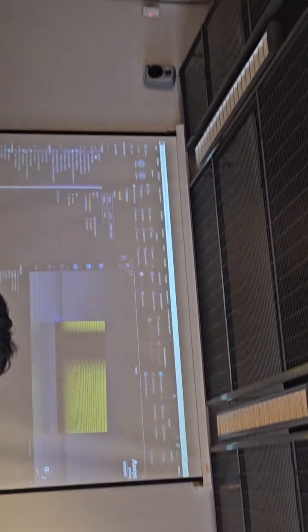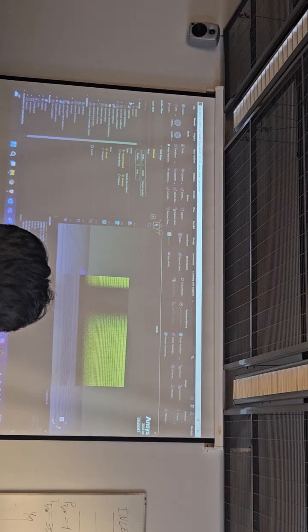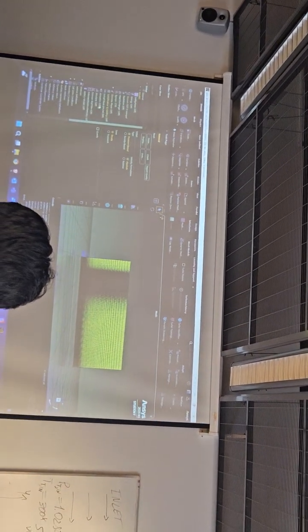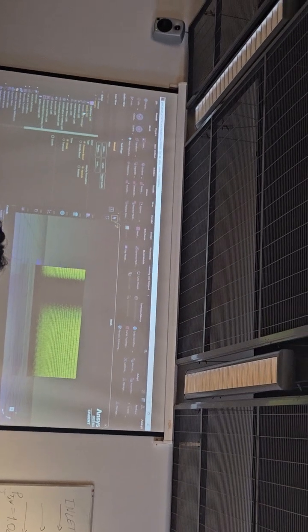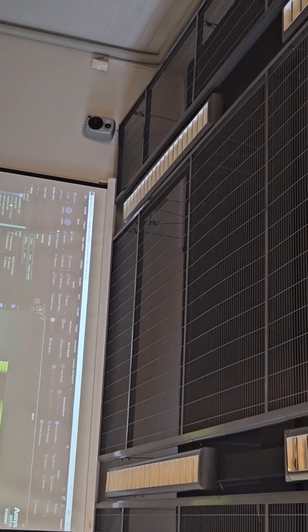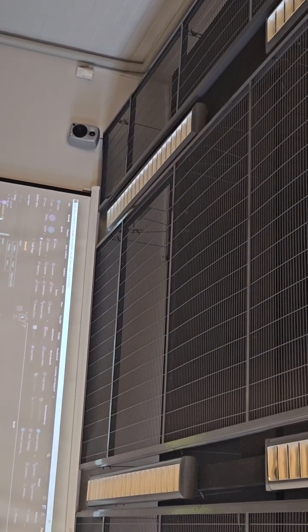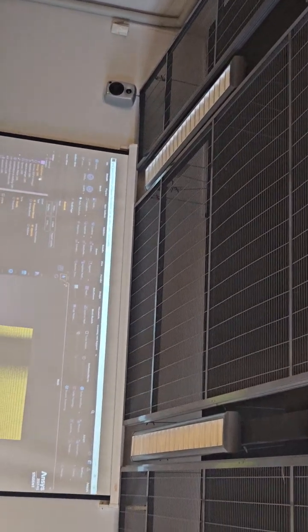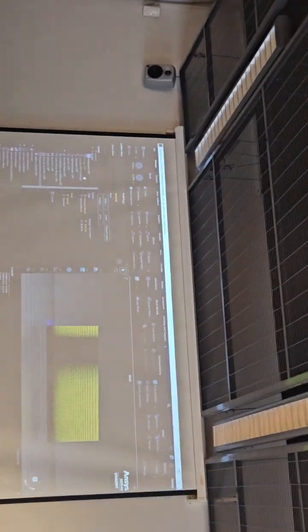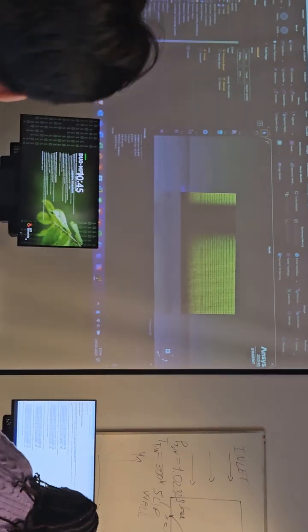Then, what could we model first? In models, if you expand, if you click on the plus, you can see that there are plenty of models. We don't really need to look at all of them, we just need to look at the viscous model, that is the turbulence model, and the energy in some cases. So in this case, we have an incompressible flow. The energy equation is not really crucial to solve the flow, but still, I typically use a flow formulation that includes the energy equation.